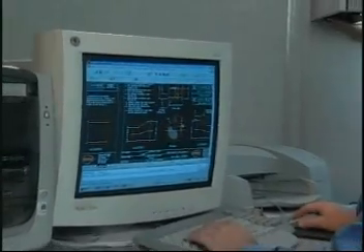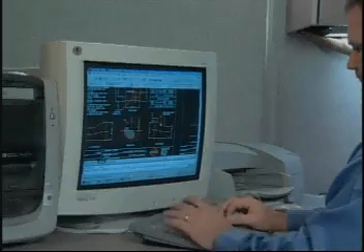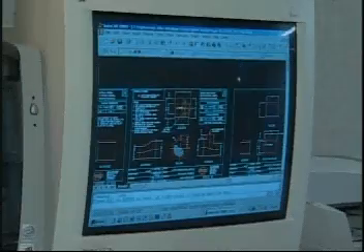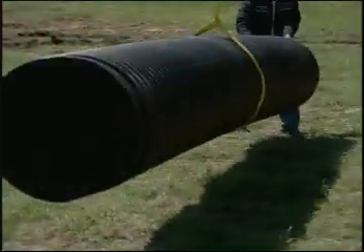On the other hand, reinforced concrete pipe is manufactured to a standard class or a specified design strength using either the indirect design or the direct design method. This allows the design engineer to determine the amount of structural strength to be provided by the pipe versus the strength provided by the embedment soils. This often means that the contractor can use the existing in situ soils for embedment, even when the soils may not be considered to be higher strength.